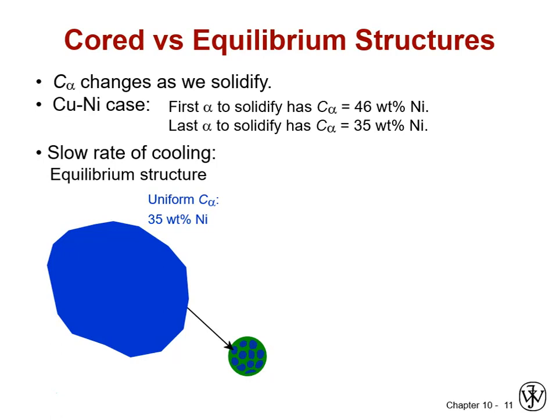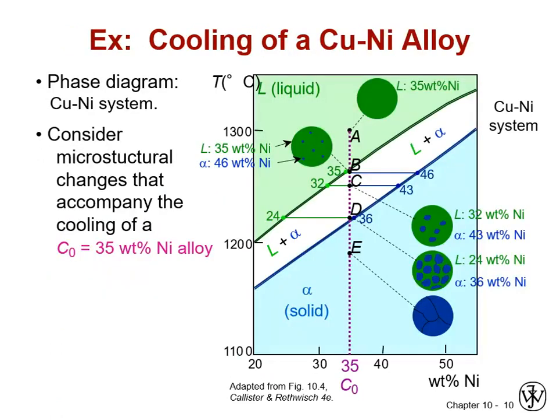So in this case, what we're doing is diffusing copper and nickel back and forth across our growing grain, because the new material that's depositing, we saw from our phase diagram, is not the same. Every new layer of solid that we add to those precipitates has a little bit different concentration. It's a little bit richer in copper and poor in nickel.